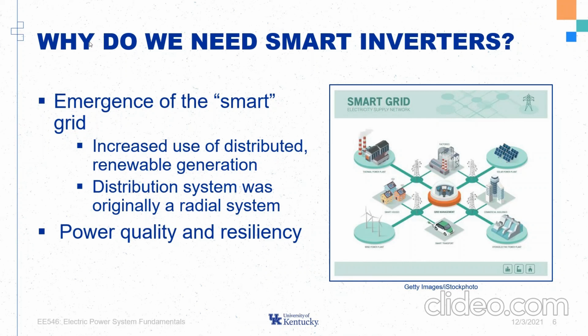When they produce electricity, they turn a turbine, which turns a mechanical shaft, which produces alternating current automatically. However, renewable sources, like wind and solar, produce direct current. Therefore, with the increased use of these renewable energy sources to connect them to the grid, we need to use inverters to convert the DC current that they produce to alternating current.